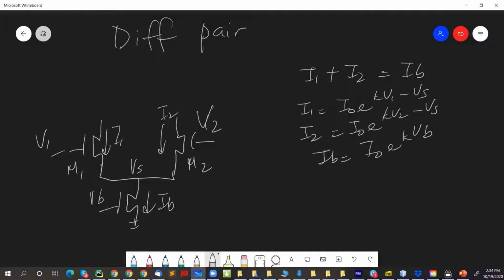Yeah, usually when you do analysis, you assume it's the same. Of course, you have to assume that all the transistors are equally sized, right? And it's not exactly the same, right? Because the top transistor of the source follower has a source that's not tied to ground. It's actually tied to V out. And if you know about this body effect, if the source of the transistor changes, then it effectively looks like the threshold of the transistor is changing.